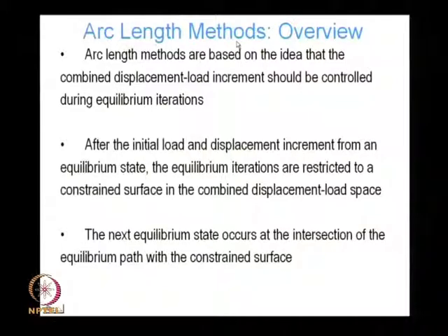We have various arc length methods, for instance Riks' method and things like that, which are important for any advanced finite element code. You will have these methods if you are interested in computing things like post buckling solutions. I do not want to talk too much about solid mechanics or any particular application, but arc length methods are necessary when my solution curve encounters these limit points, which results in my Newton iteration failing.